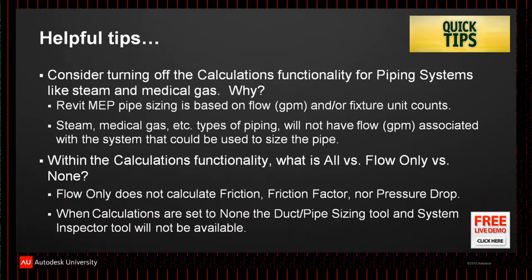The other thing too, how many people know that you can actually shut the calculations off inside of Revit MEP? You can actually turn the calculations off. So, for example, let's go back to the institutional project. Most institutional projects have what? Steam, medical air. Steam is based on what? Pounds per hour. Medical air is based on what? SCFM, standard CFM.